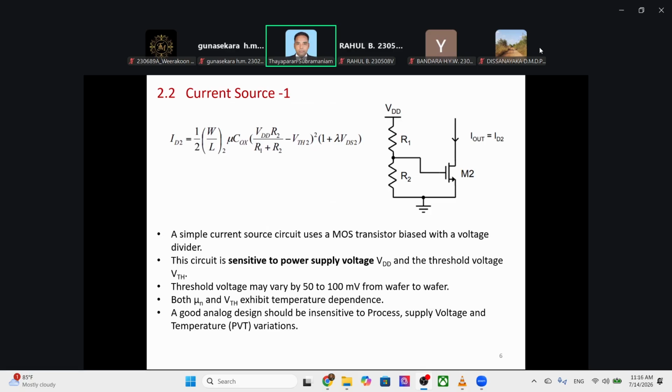Right. The point is we are not considering the delay too much here, but the shift in the characteristic curve. For example, when you set VGS equal to 2 volt, what is the current? Say the current is 2 milliamp, but if you have different PVT, it may be 0.8, depending on the PVT condition set here, in simple terms.